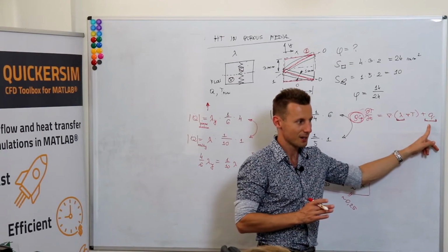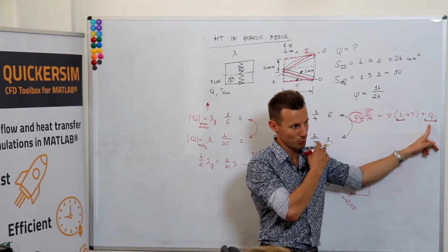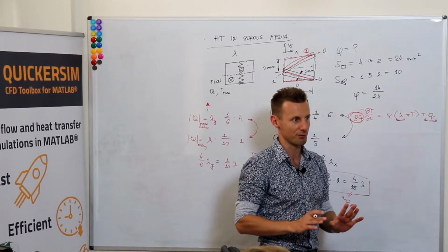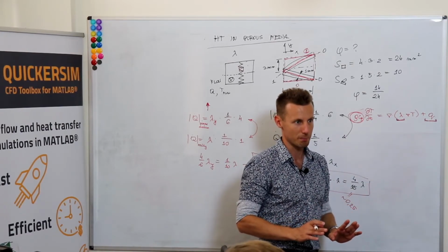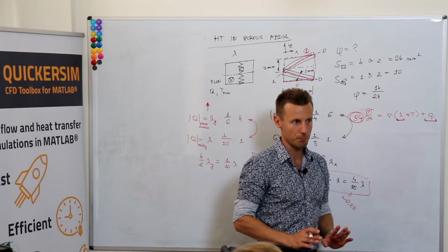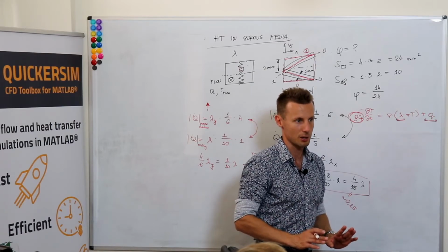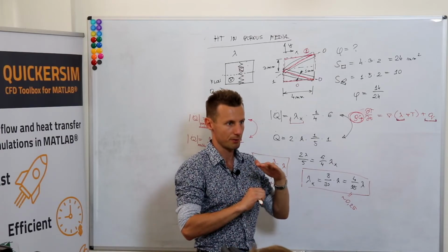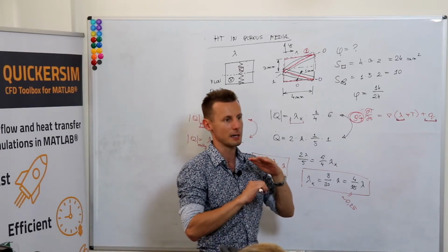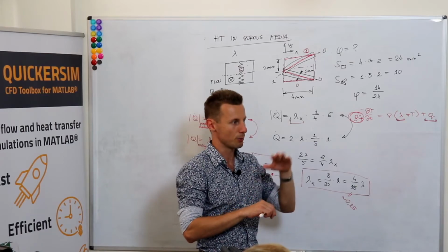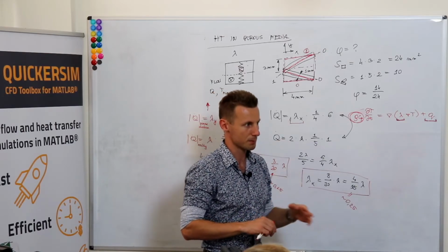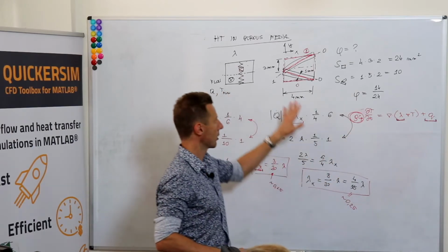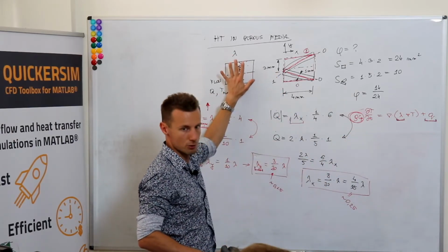And again, do not be misled by what we've been discussing previously, that at the solid-fluid interface you don't impose the boundary condition. We don't impose the boundary condition in such a case where you represent both subzones within the same domain and with the same equations. But here, we clearly do not represent both zones because we are only solving for the solid structure.